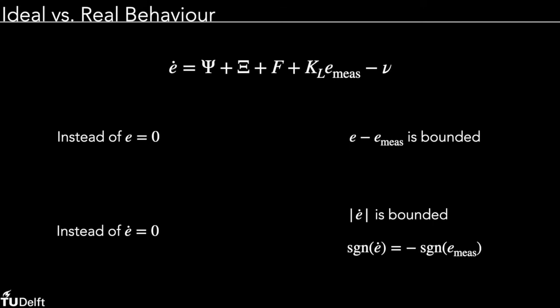With this design, we implemented the observer and the accompanying threshold on the oscillatory fault case in the elevator servo. But it turned out that this approach is too slow to provide detection in the region with higher oscillation frequency. And this turned out to be mostly due to the filter which is required to get a useful residual from the switching term.